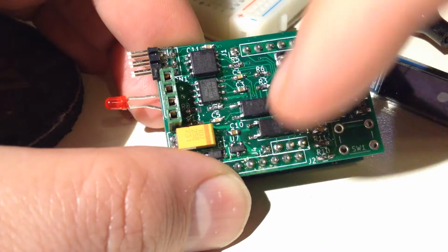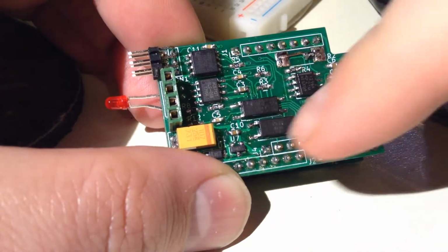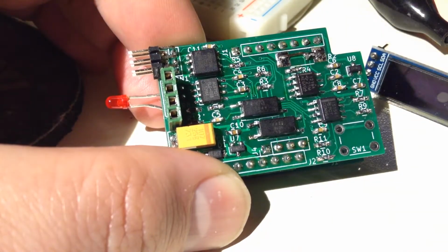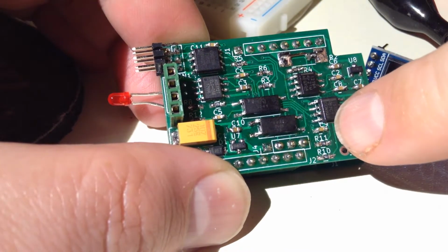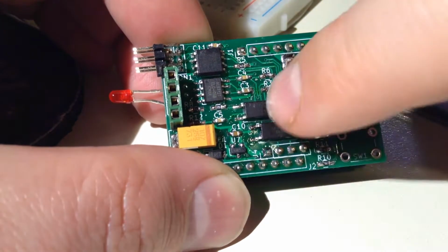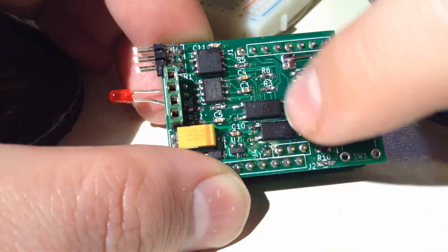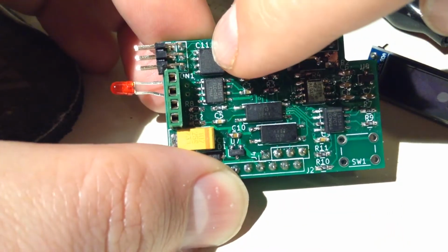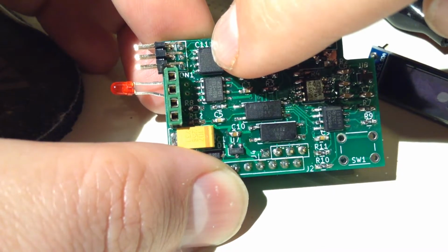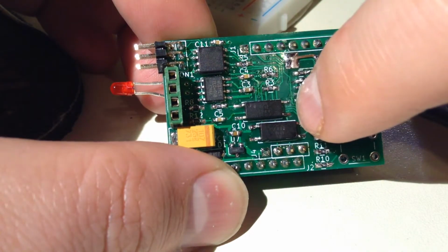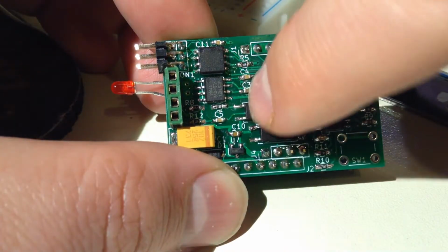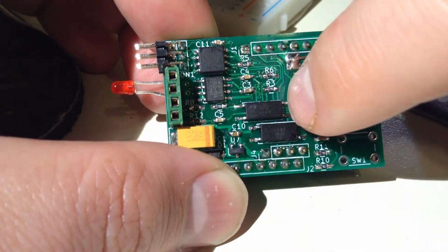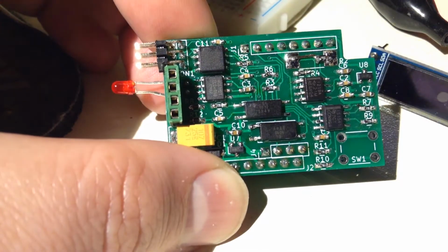Well, that's these three guys here, this one, and this one, they are isolation devices. This one isolates the I2C bus, and these are basically giving me control. So the microcontroller can say switch the output here via this one. It basically controls one of these pins, and then this output is clamped together in an isolated manner.